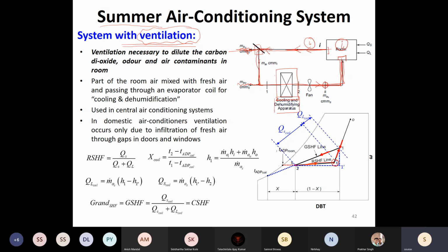Now what is happening outside is this mixing is happening. So this is still at condition I, assuming that all the ducts are perfectly insulated and no leaks in the duct. And this is the outdoor condition. So this I and O is getting mixed ahead of your cooling coil in a certain ratio to give this state 1. This is the state 1. And now your cooling coil is not seeing I, which was the case in your residential AC. It is actually seeing a load equivalent to state 1.